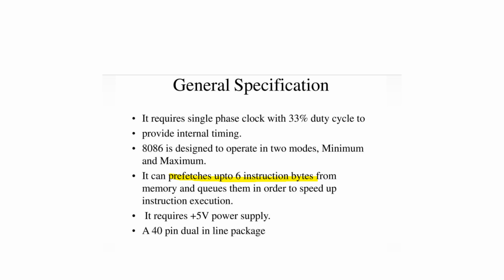It has a pipelining architecture in 8086. It is not available in 8085. Technically, in 8085, it takes one instruction at a time. First it will do the opcode fetch for LDA 4500. It takes that LDA as the opcode fetch, and then for 4500 it does memory read, and then another memory read. It will do it one by one, and then it will execute.